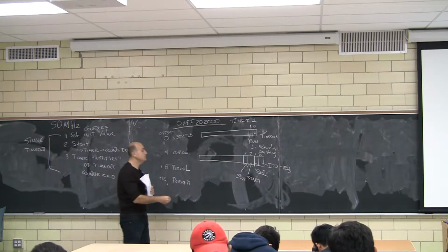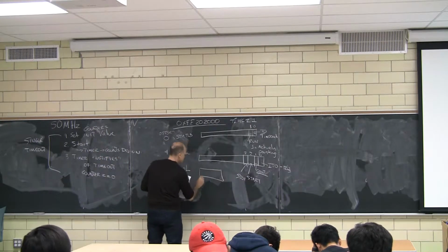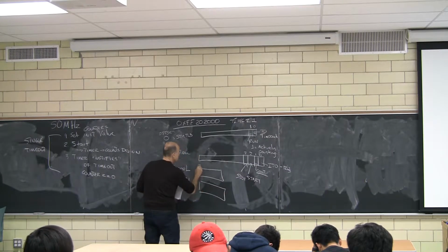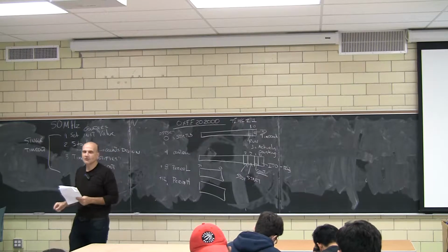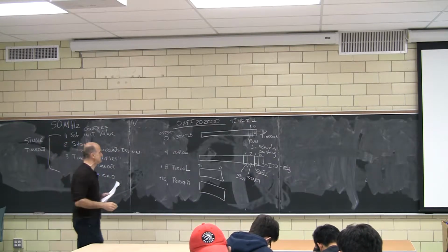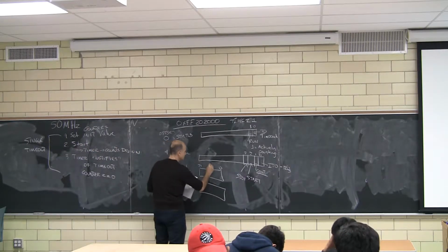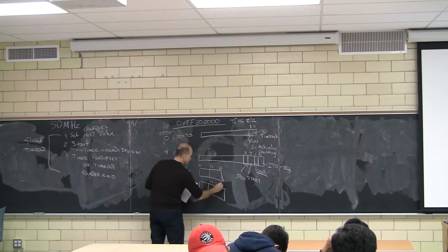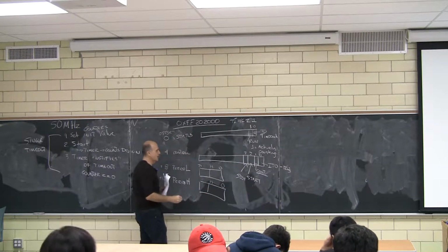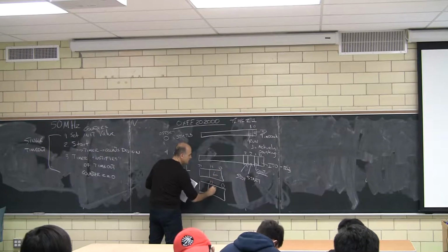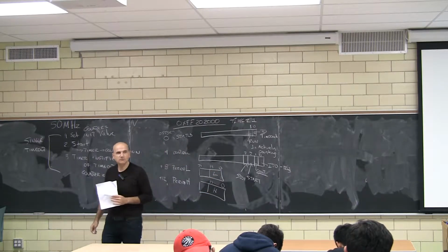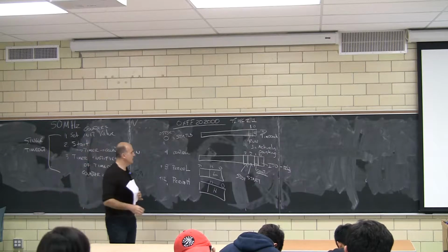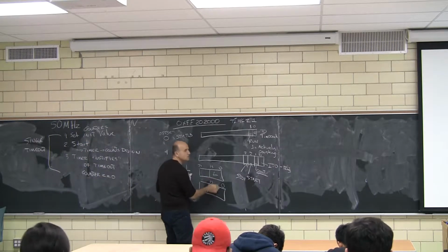Both of them are 32-bit registers. However, only the lower 16 bits are in use. This would be the low, this would be the high part. The actual value you're asking the counter to count down from is the concatenation of these 2 lower parts.